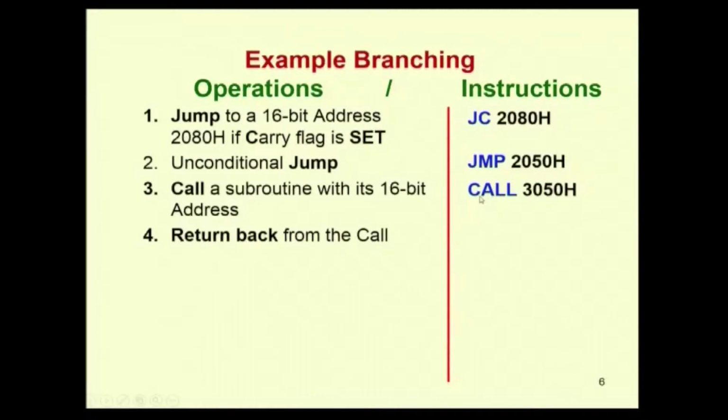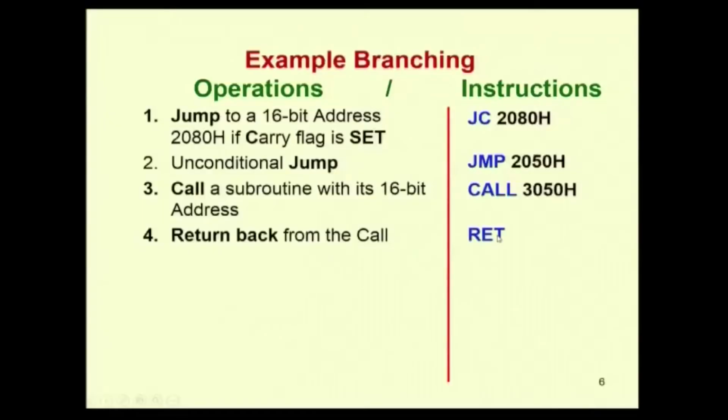We will see in the coming lectures about the stack pointer and how the microprocessor remembers where it has left the program. Once it encounters the return instruction, it will take the return address which has already been stored in the memory location called the stack, and then return back to where it left the main program. So, that is the return instruction.